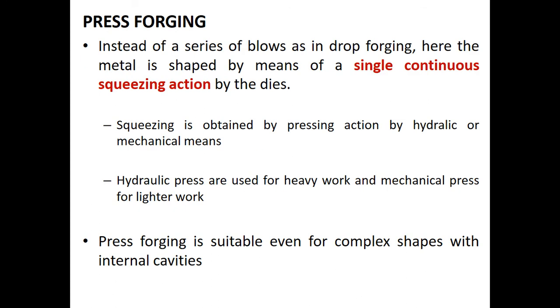Another important operation is called press forging. This process is similar to drop forging, but the method of application of force is different. Instead of a series of blows as in the case of drop forging, here the metal is shaped by means of a single continuous squeezing action between the dies. That's the peculiarity of press forging.